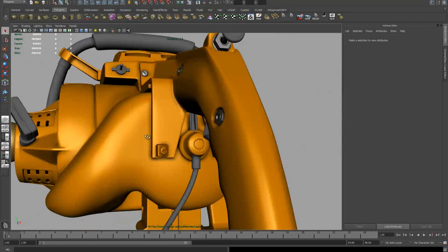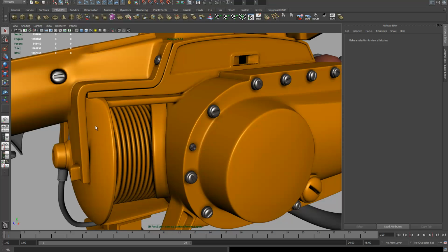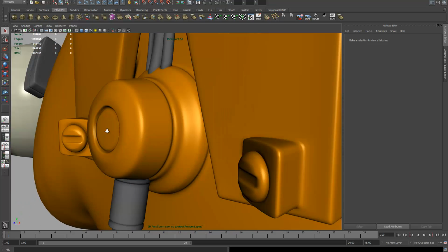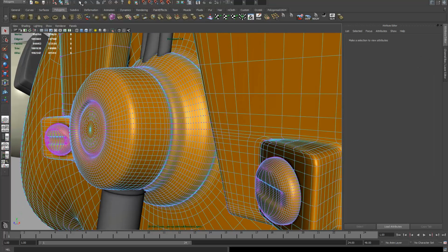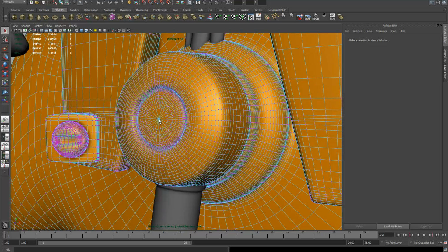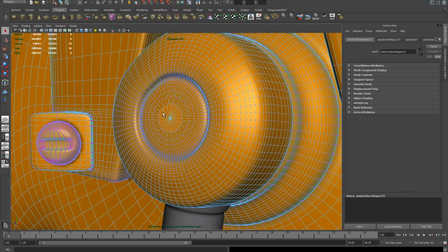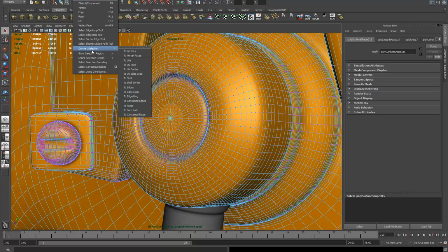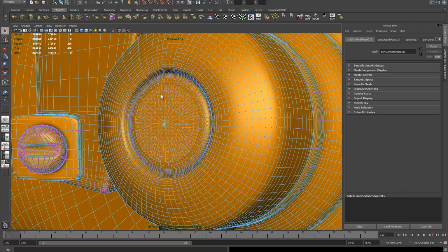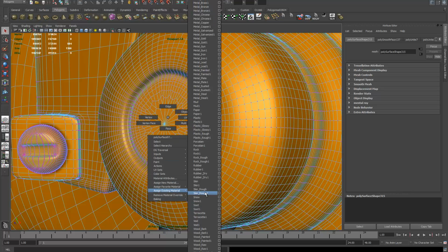And you can also go into face mode and just apply a certain material to some parts. For example here, I'm gonna select this little surface here. I'm gonna increase the selection. It'll grow the selection. And I want this to be, let's see, rubber.